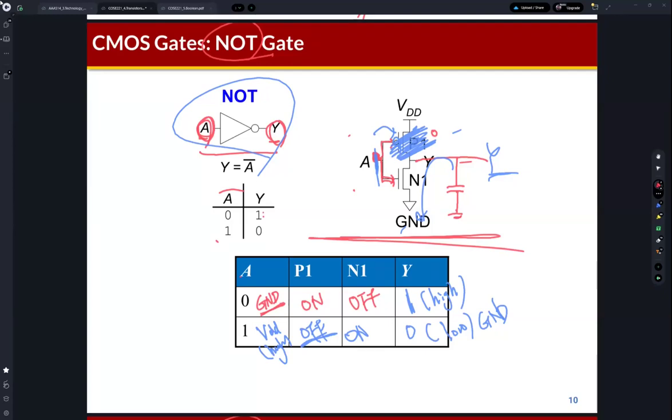If a gate signal is set, then the NMOS or PMOS transistor can be connected or disconnected, so the output can be high voltage or low voltage. For this circuit, as you can see, we can implement an inverter circuit using one PMOS transistor and one NMOS transistor.